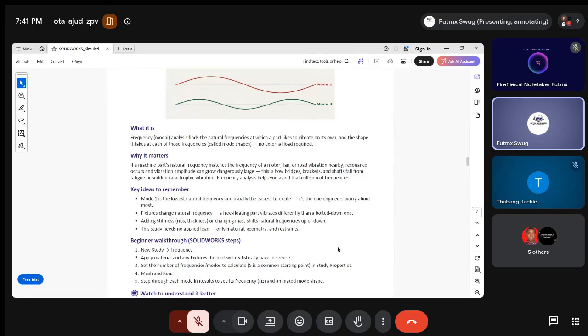I think I did a design at work where we needed to add a dummy load inside the CubeSat to balance the weight and reduce the frequency of oscillation. Those are some of the techniques you need at times to make sure that you have distributed frequencies across your design.